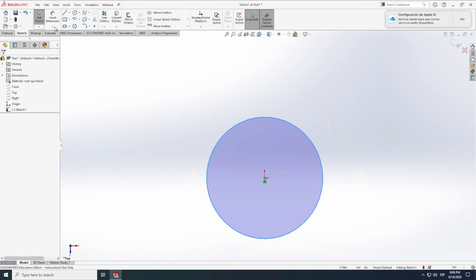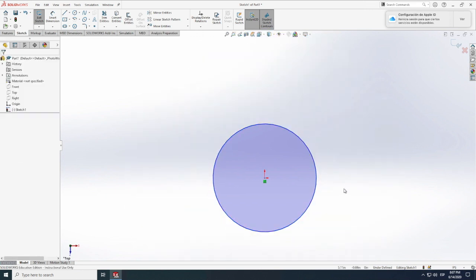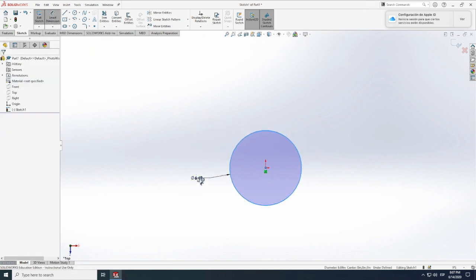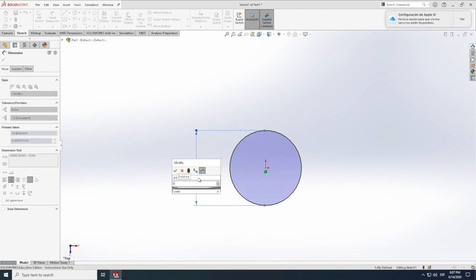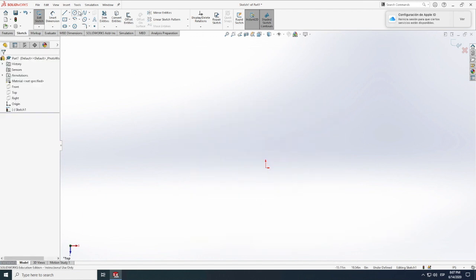As you see, if we do not smart dimension this circle, you'll be able to click in it and drag and make it bigger and smaller, which we do not want, because that might complicate your future sketches. So let's go ahead and smart dimension that. Let's go for 5 inches. Let's eliminate that because we don't want it yet. And then here you can see you can do perimeter circles, but I won't cover that one because it's rarely used. Then here we got rectangle, right?